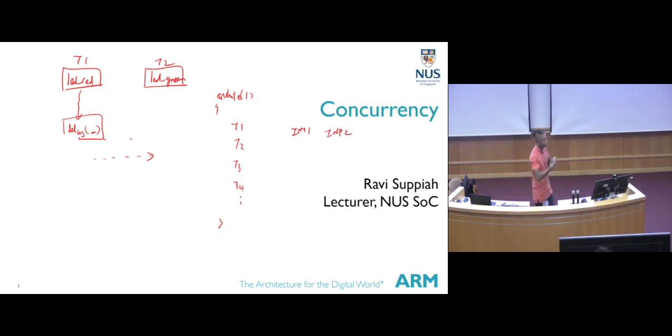Now, when we go in this direction, where everything can happen concurrently, it leads to another challenge: how do I synchronize? When I do things sequentially, that ensures everything goes in a flow: activity 1, activity 2, activity 3 and so on. But now that everything is concurrent, how do I synchronize the behavior? How do I ensure that when the motor stops, then the LED turns on, or when the audio is playing, the LED will change behavior? How do I communicate between different tasks?